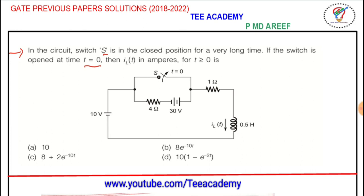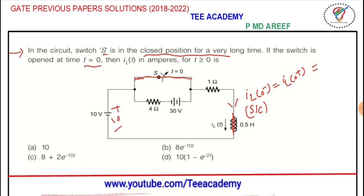Simple question here. The same formula that we applied previously, we are going to use now. Before the switch is closed here, a long time means it is short circuited like this. Which is short circuited means the inductor also acts as a short circuit. When the inductor acts as a short circuit, what about the current here? So let us assume IL of 0 minus is equal to IL of 0 plus, which is equal to what here? Here we have plus minus 10 volts,